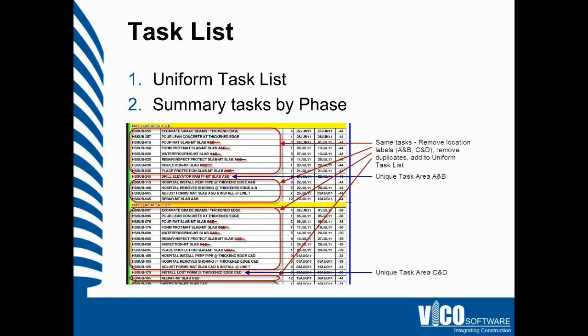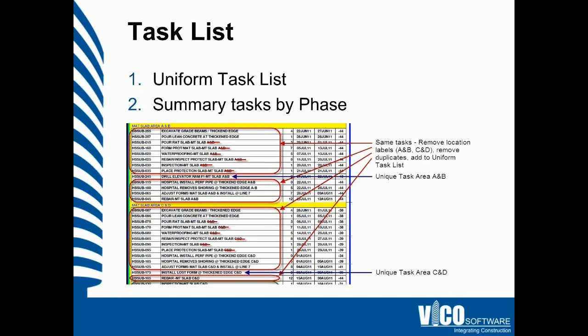This process allows us to identify any unique quantities which are currently not tracked, and poses the question: do we need to track this quantity as a unique line item or not? And again, all of this is driven automatically by having a model available, which will tell you exactly all the pieces that are contained in that model and should be considered for representation in your schedule.